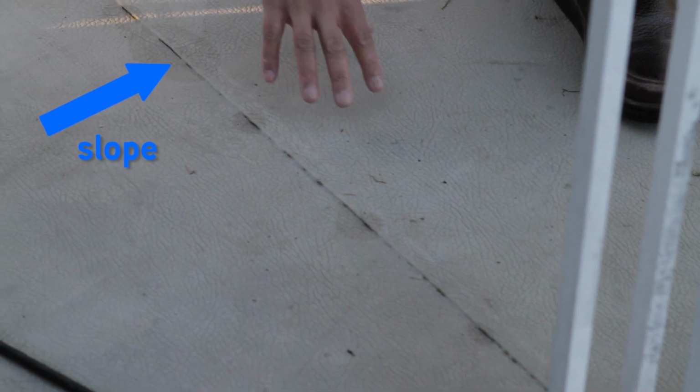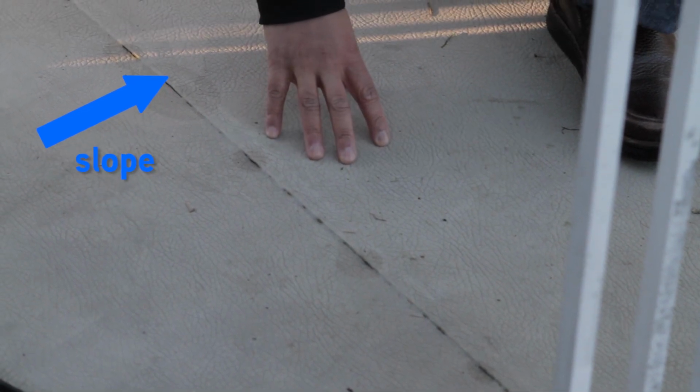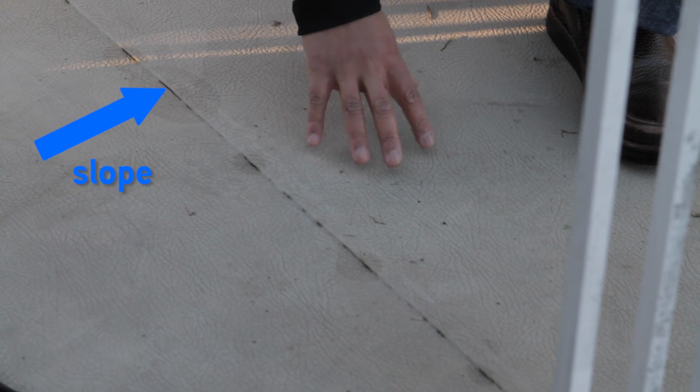Another thing that you can look at when you're on a balcony is how well it's sloped. Now this looks like a well-sloped balcony. However, in this case, we look like we might have a negative lap. And what that means is this part of the membrane was installed after this part. So we have a little bit of a negative lap here, which means it's possible for water to get in between these two membrane sections.